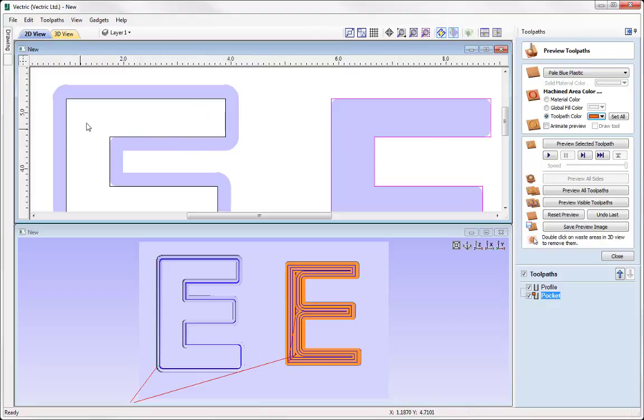Now, when we're cutting the outside part, we will always get radiused internal corners because of the shape of the tool. And when cutting inside the part, we're always going to get sharp internal corners, but we're going to get radiused external corners like the ones that you can see over here. And so we really are presented with a mismatch of internal and external corners when we're trying to slot one part into another. So we can see where we have a nice sharp corner here.